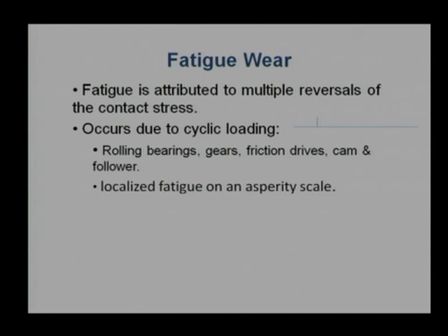But when it is changing position from straight to the bent position, it is subject to stresses, tensile stress and compressive stress, and this happens a number of times during the sliding motion. So, truly this is a bending problem. Now, I can deal with this as abrasion, or I can deal with this as adhesion, it does not matter. The basic micro level phenomenon is fatigue failure.